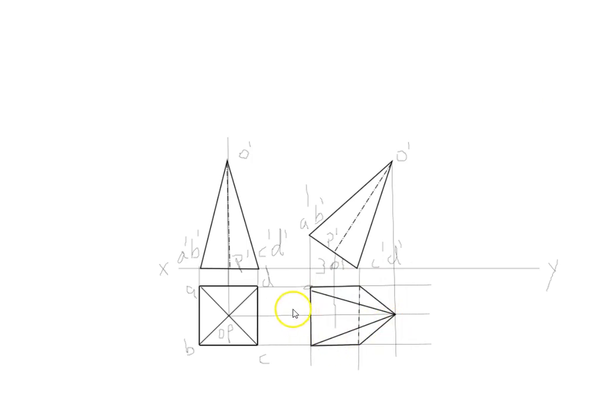So while drawing projections, the dark continuous lines should be much more distinct from the projection lines you have drawn. Otherwise it won't be neat, and it would be difficult for someone to find the difference between your projection lines and the actual projection. So this is something you'll have to keep in mind.